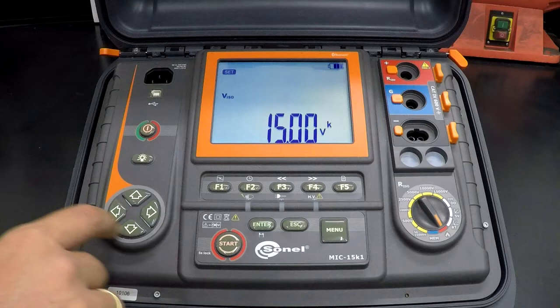One more unique feature which I didn't show is the partial discharge indicator. The partial discharge indicator is available in every measurement method. When the measurement is already in progress, please push the F4 button so the screen of the discharge indicator appears. This method is presented in the official Sonel movie.